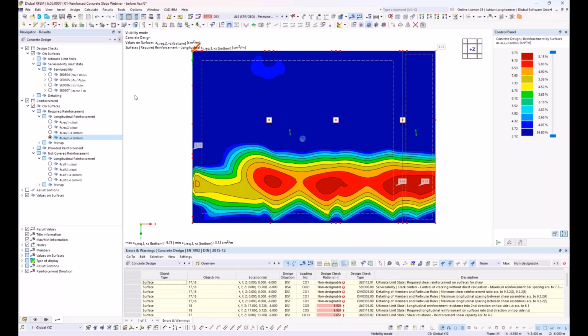It could be good to define the existing reinforcement more accurately, but also if you would like to do design checks for crack width and so on, or if you use these other design checks, these are done based on the existing reinforcement, and it is possible to define this existing reinforcement more detailed, and this I would like to show now.